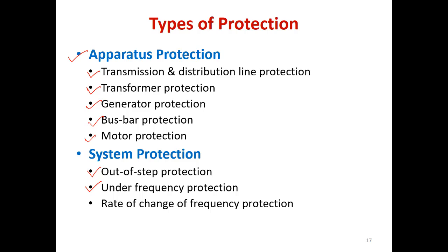Rate of change of frequency protection: when the rate of change of frequency is very high, then sometimes the protection schemes take action. In fact, nowadays we have high speed phasor measurement units which capture these signals for rate of change of frequency protection, and because of that the protection scheme acts.